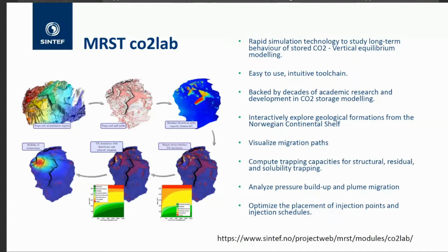So then we make the assumption that actually this happens instantaneously, and we model numerically the horizontal fluxes, but we analytically calculate the vertical configuration of the fluids, so the thickness of the CO2, based on the results from the horizontal numerical simulation.